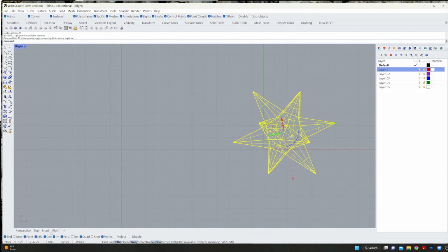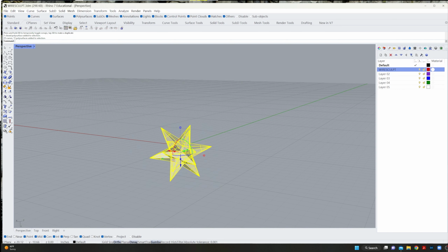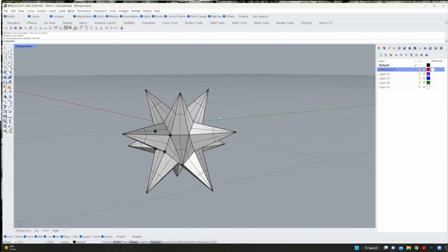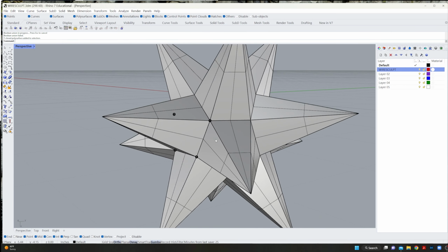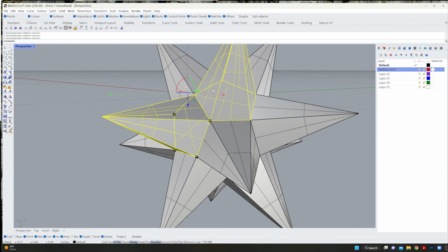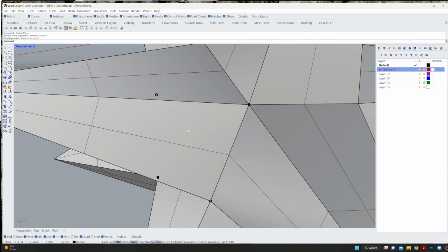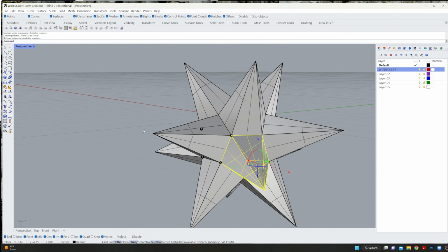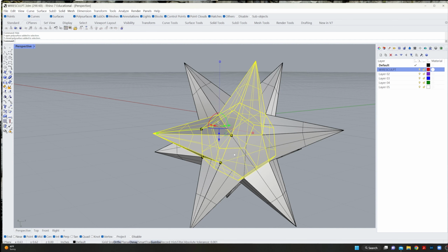And we go ahead and bring that into, well, Boolean union it all together first. Boolean union. And if it doesn't want a Boolean union, sometimes you got to Boolean union a couple at a time. Well, if it doesn't want a Boolean union, what do we do? It can't do edges to edges. So let me just hide. And then Boolean union these two together.